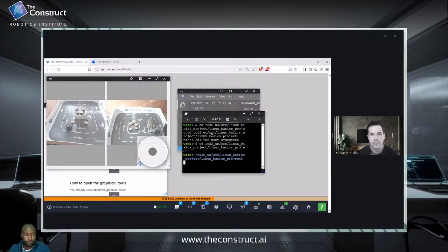It checks if there are any obstacles in the way via a threshold variable, which I have set to 0.3 meters, if I remember right. If it gets a laser reading greater than that threshold, it will move forward, not even a meter, less than that actually.